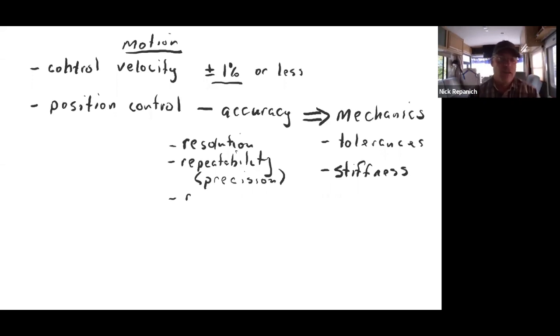And so you just tell it, no, don't go so far, back off 4 motor steps. And then you do the move again. Oh, there it is. It's right in the right spot. Boom, boom. And so now you have a repeatable action, and you can program in what looks to be an accurate motion, but the only way you got there was because you had the ability to adjust.